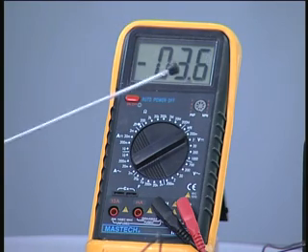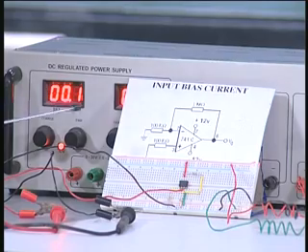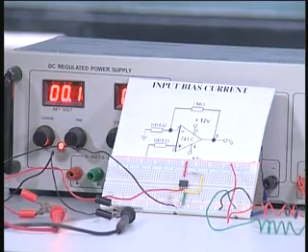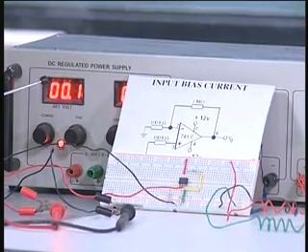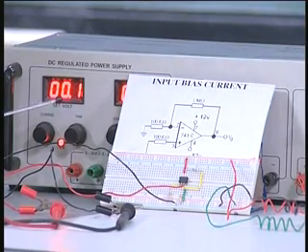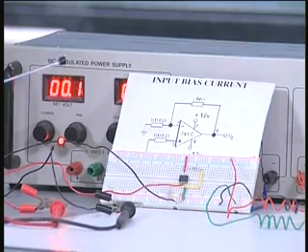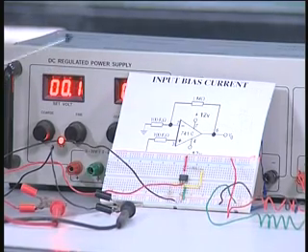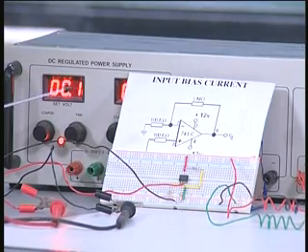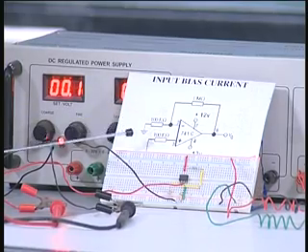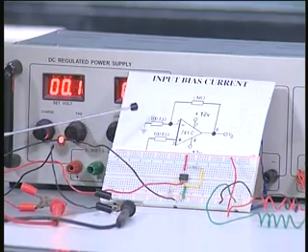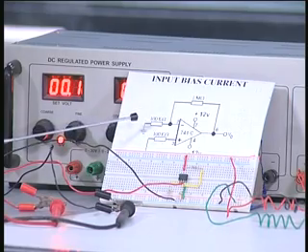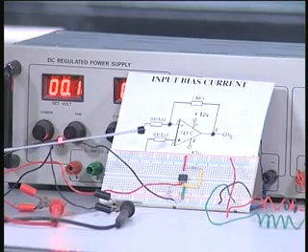So you have about 37 and 47 nanoamperes, and the difference, which is called the input bias current offset, is 47 minus 37, so it is about 10 nanoamperes. In the example that we saw, it was about 5 nanoamperes they are given, so it is of the same order, it is about 10 nanoamperes, that is the input offset current that we have. That means the difference in the current between the two terminals corresponding to inverting and non-inverting